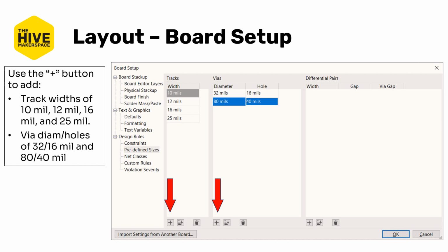I like to keep my trace sizes, my minimums, above the minimum value if at all possible, which is generally around 6 mils, but it could be a little smaller depending on the fab house. And this reduces the possibility of broken or damaged minimum width traces and traces that are more likely to see issues. For signals, I generally try to use 12 mils and then neck down, meaning shrink briefly if necessary, like between paths or something, to about 10 mils.